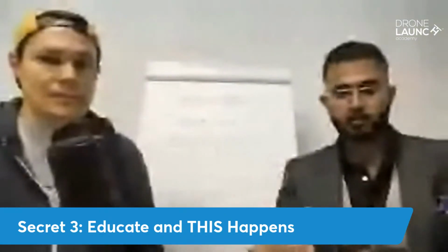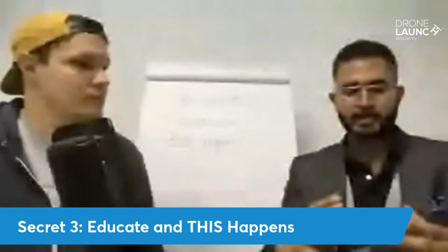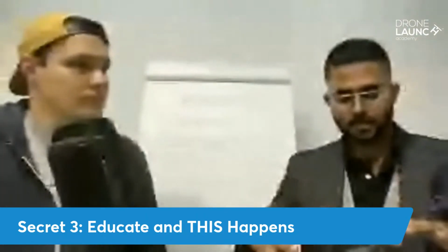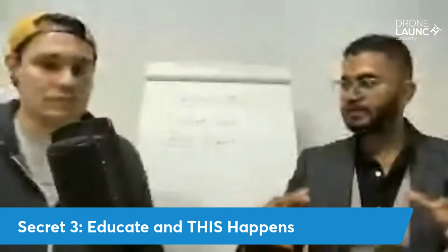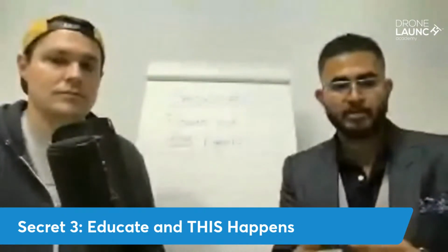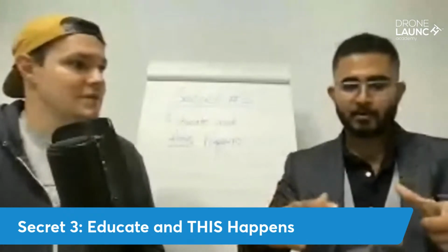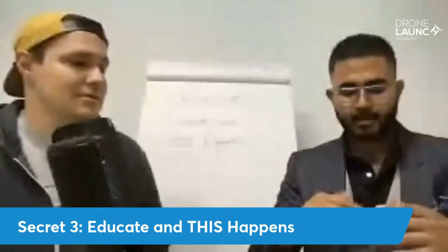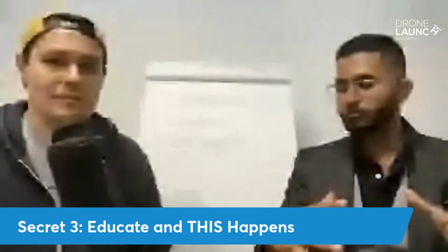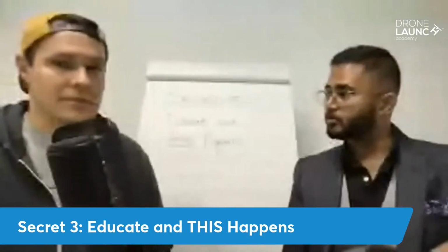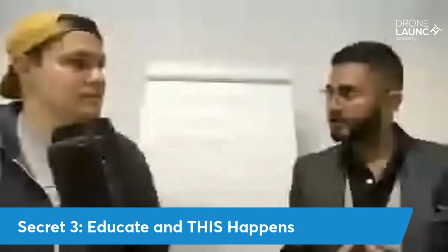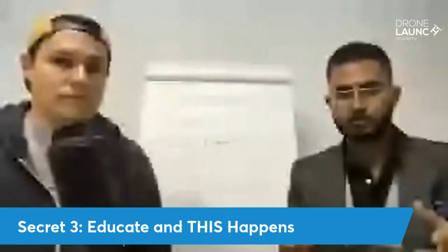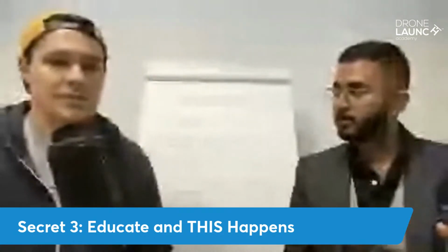So we created the orthomosaic. If you don't know what an orthomosaic is, it's one big picture combined from hundreds or thousands of pictures put together, where you can do measurements, kind of like Google Maps. Google Maps is a massive orthomosaic of the world, but they use satellites. We use drones, flying at a much lower level, take pictures, and combine them into an orthomosaic map. Now they can count the inventory and look at the entire property in one picture, zoom in on any point, and it does not distort. It's very accurate and very clear.